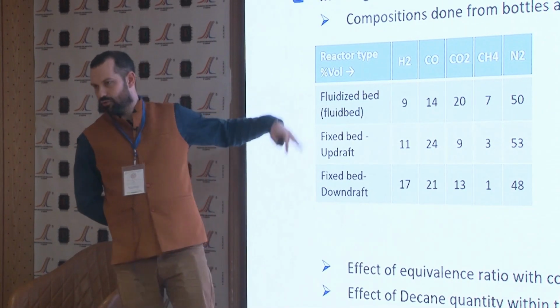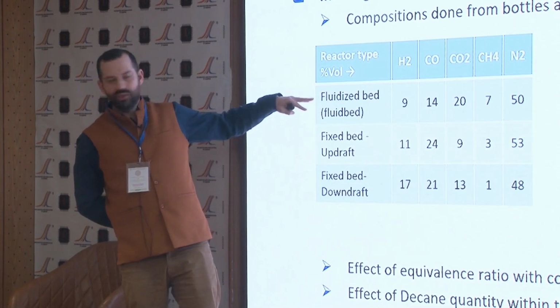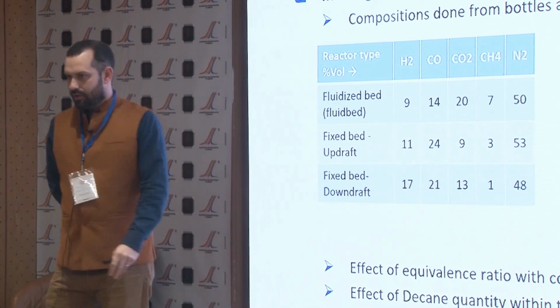And this was really the most difficult to stabilize. So suppose we go more hydrogen rich. Probably faster combustion, so easier to stabilize. If we think about a spark ignition engine, you will get higher flame speed also. So normally we should have benefits.